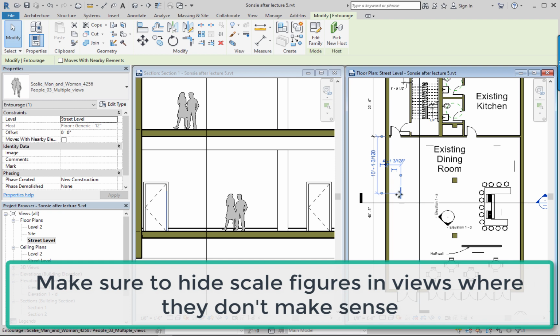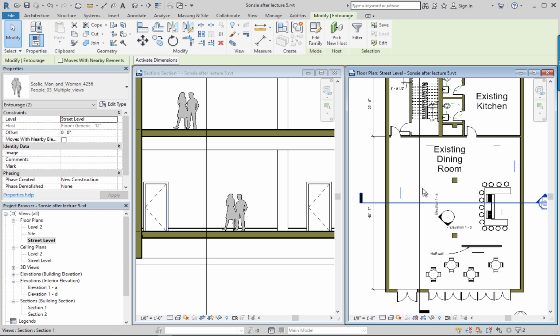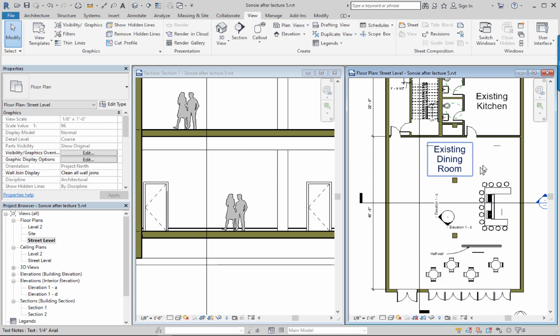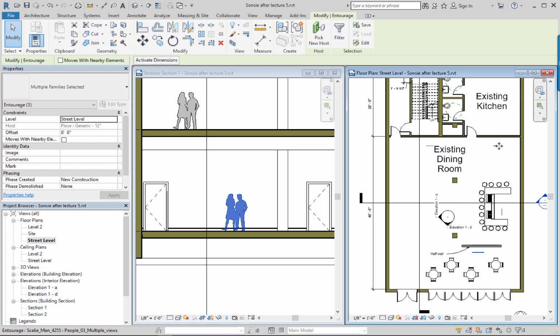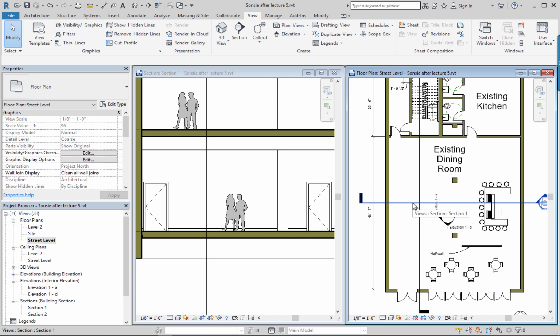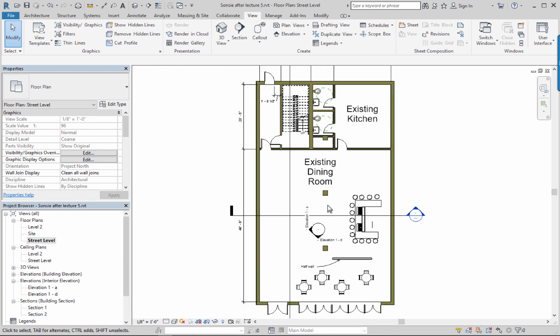Okay, and this is a kind of let me just select all instances visible in this particular view, and then I'm just going to hide them. Okay, you obviously don't want. Oh, except I've got these other guys that are apparently a different family type. Anyway, we'll hide it again. Oh, and here we go. Repeat hide elements is a quick way to do that. There you go. That's the basics of setting up, kind of preparing for printing.